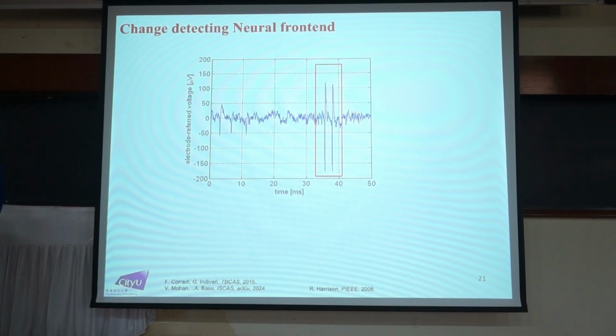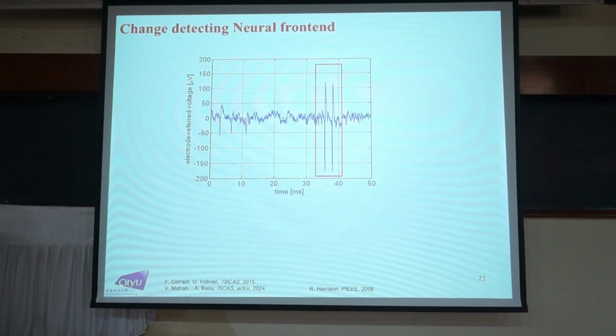So if you see this, you can see that if you are only interested in these signals, why would you want to send data corresponding to the others? In other words, if these big changes are the ones that you want, then potentially I can have a change detection circuit that sees if the change is bigger than a certain threshold, and only then I will send that delta.